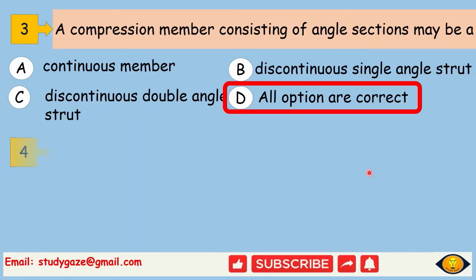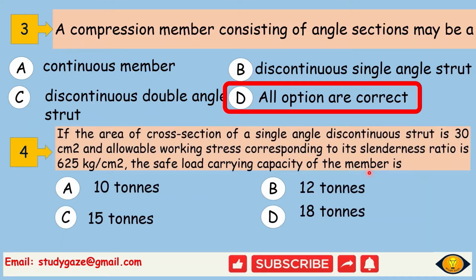Next question: if the area of cross section of a single angle discontinuous strut is 30 cm square and allowable working stress corresponding to its slenderness ratio is 625 kg per centimeter square, the safe load carrying capacity of the member is. The safe load carrying capacity of the member is 15 ton.